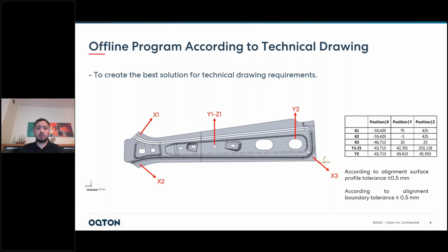If there is no scanning in your hands, you need to create a gauge or fixture to check the points of the surface profile, but it could be just one point or two points. With scanning in Control X, you can easily check all points of the part.